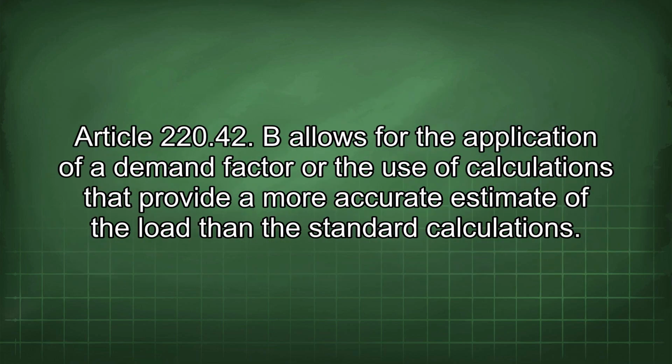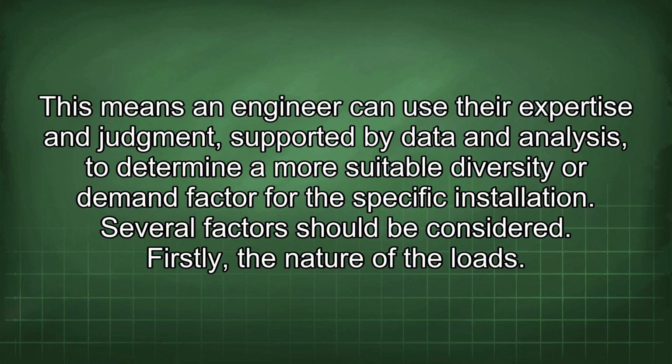Article 220.42(b) allows for the application of a demand factor or the use of calculations that provide a more accurate estimate of the load than the standard calculations. This means an engineer can use their expertise and judgment, supported by data and analysis, to determine a more suitable diversity or demand factor for the specific installation. Several factors should be considered.